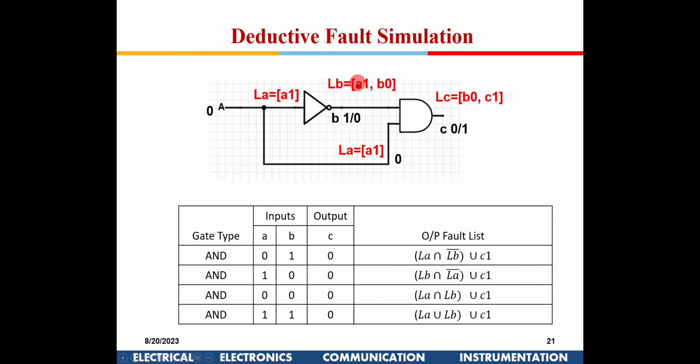So this table, okay, will be initially available with the tool, okay, for each gate, and this is the fresh net list we are providing. So it will apply these rules as it takes one test vector and keeps applying that rule. So in one run, okay, it will tell me, okay, these two faults can be detected at the output. Is this okay with all of you?